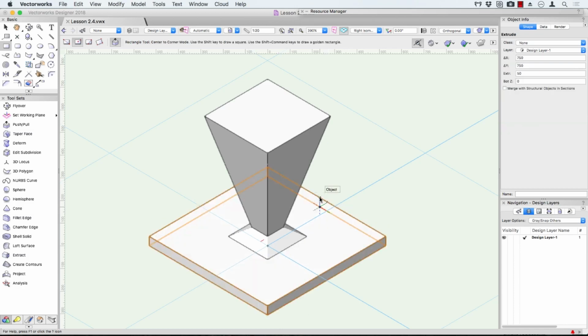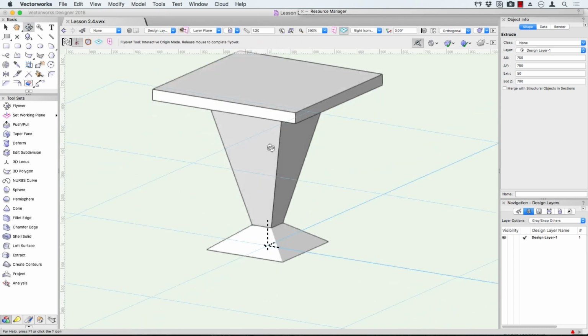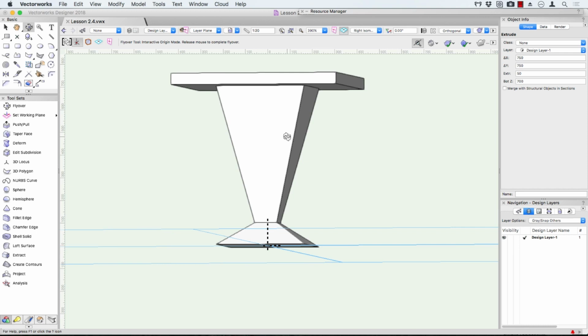Enter once, enter again. But we need to change the bottom Z of this one. So what does that need to be? Well, it needed to be 4 inches, 100 millimeters, plus 24 inches, 600 millimeters. And now we've got the tabletop sitting on top of our legs. If we haven't done it correctly, there'll be a massive gap through here. There's not, so I've done the correct mathematics.